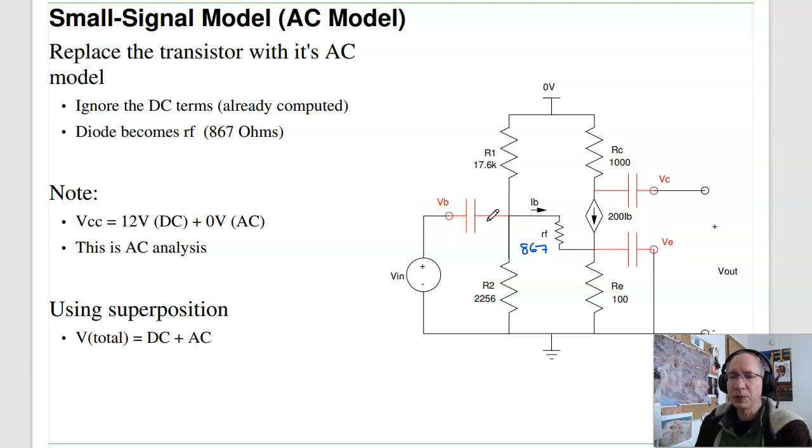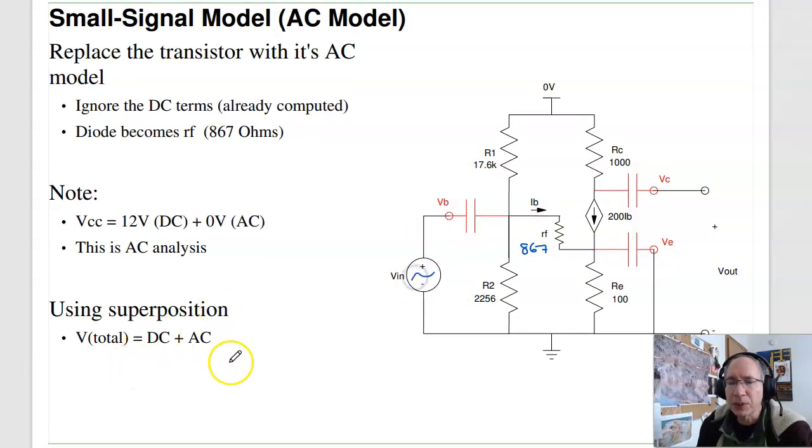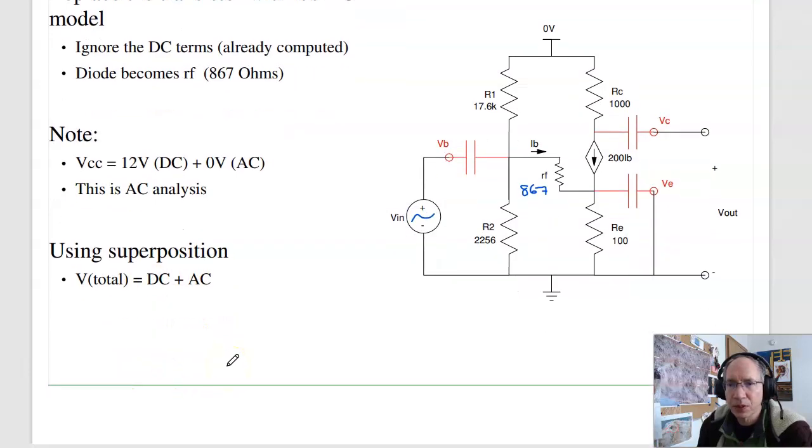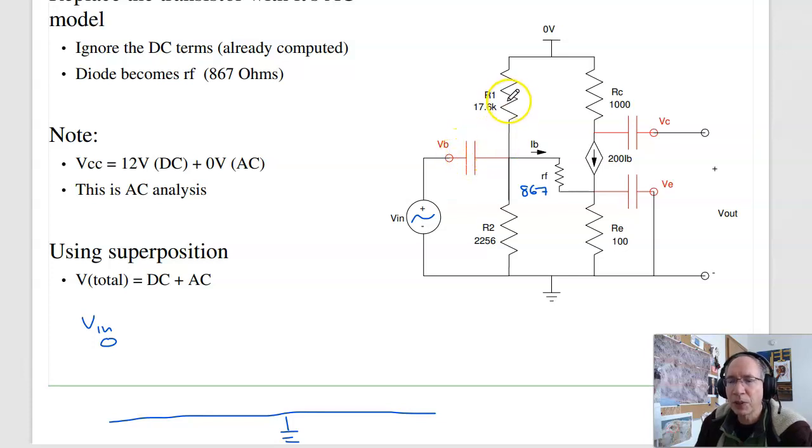So what we'll do is I'll redraw the circuit. And the way I like drawing the circuit is here's your input. Let's start from VN. Let's scroll down a little bit. Here's VN, and here's ground. From VN, I assume that this impedance is small. So this is 1 over j omega c. It's maybe like minus j 100 ohms. 100 ohms relative to 17K is small, ignore it.